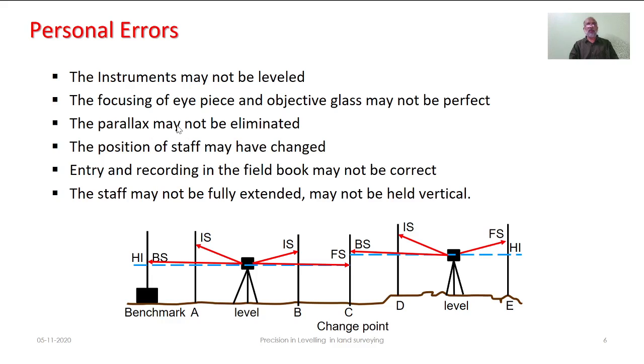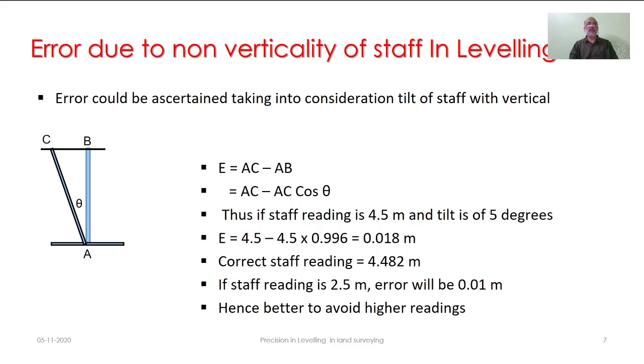It is also quite probable that while taking any staff reading, the staff position could be changed. The staff reading taken could be recorded in an erroneous manner. While taking the reading, the staff may not be fully extended. So, some such reasons could be treated as personal errors.